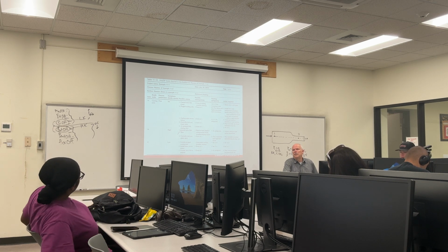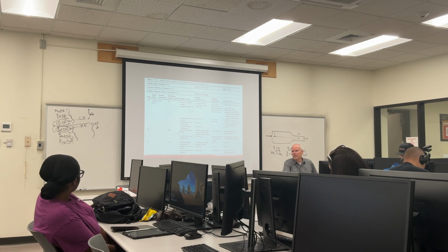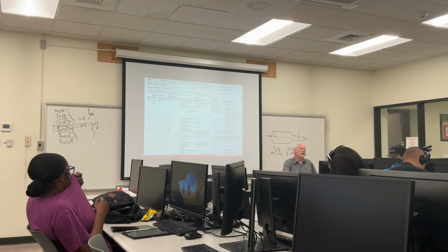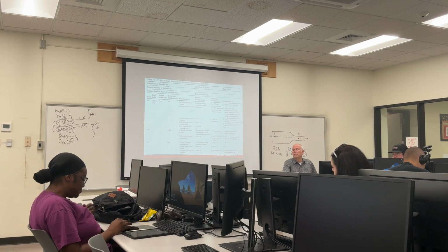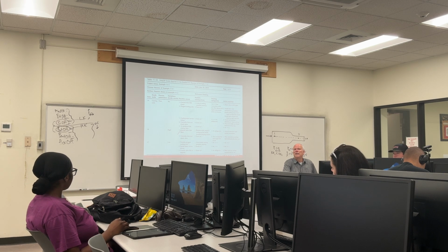Now you notice, there are no quantitative numbers here on the risk. This is just saying this is something that can happen. It doesn't say how often it can happen, what's the probability it's going to happen, or what's the probability, if it does happen, that something bad happens, right? That's all a HAZOP is. All we're doing is coming up with potential scenarios that would cause risk.